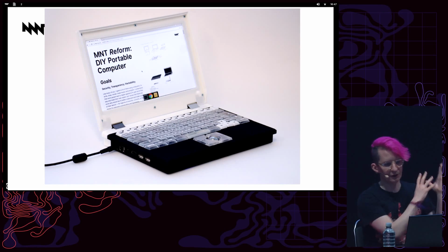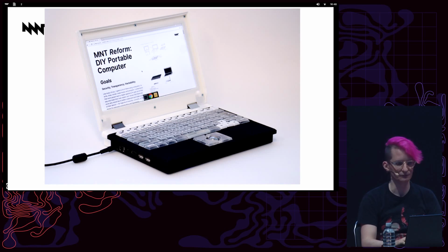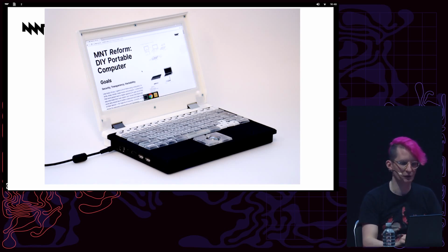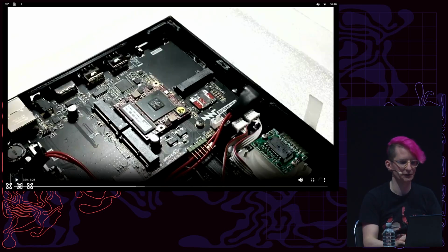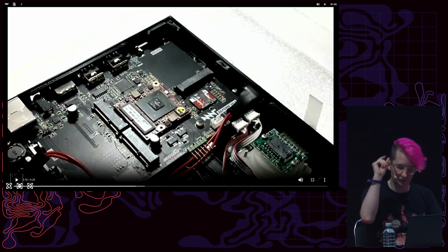We refined the box into something more laptop-shaped, and I started to work on a custom motherboard in KiCad. The IMX6 dev kit I was using before was actually two boards, a carrier with all input-output ports, and a tiny stamp that had mostly only the processor and the memory itself on it. It's in the middle of this photo if you squint.